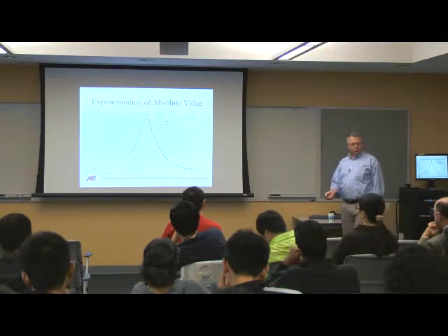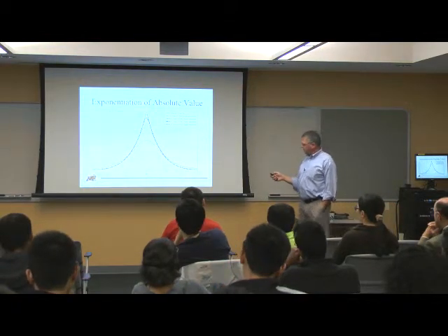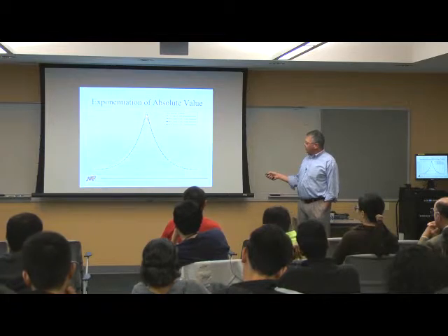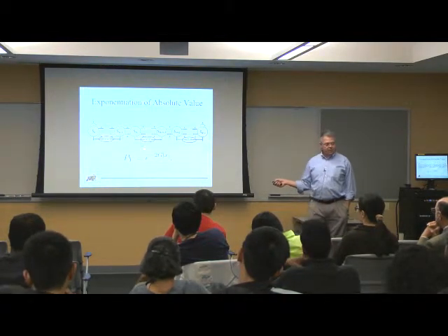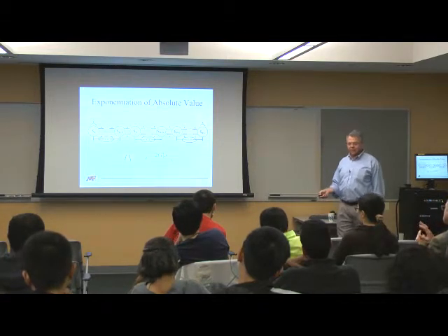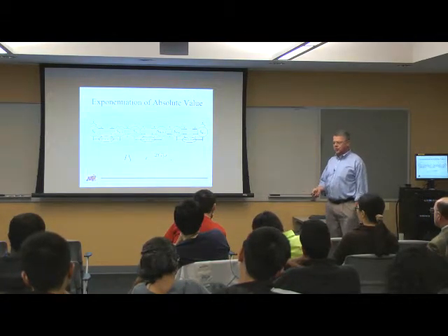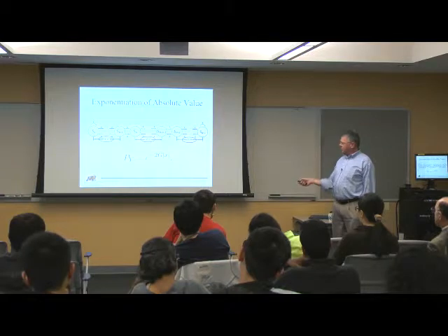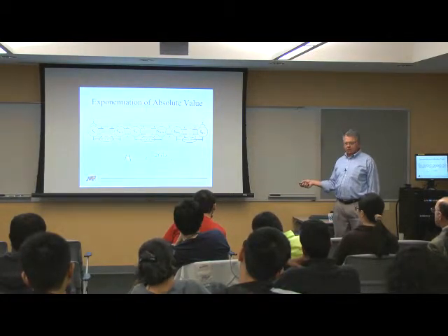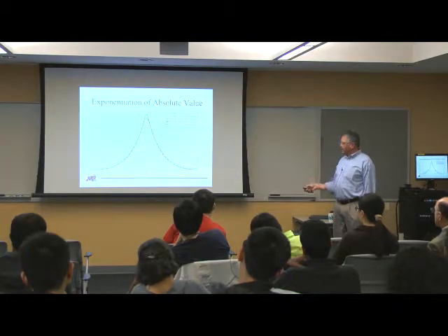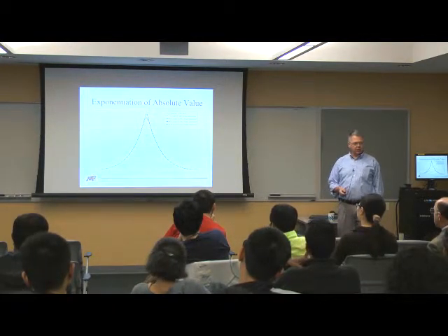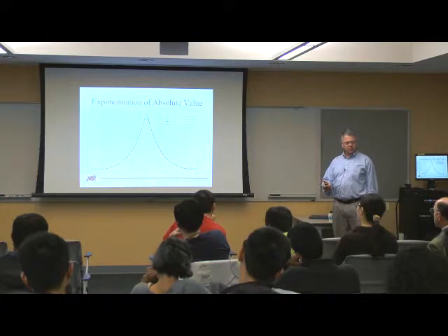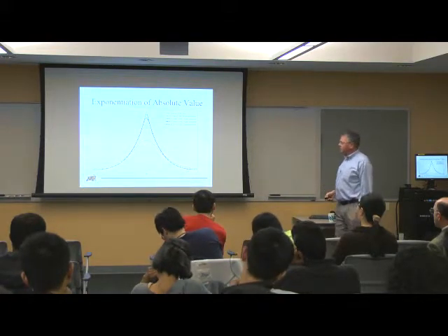So with a 64-state machine, I get a pretty good approximation of this relatively complex function. Right? I have to do an exponentiation and take an absolute value. If I tried to implement that in conventional logic, that would be a very expensive thing to do, ideally. In my case, we're just going to say, well, let's approximate it. We'll get pretty close, but we're not going to be perfect. And we can do a very complex function with very simple hardware.